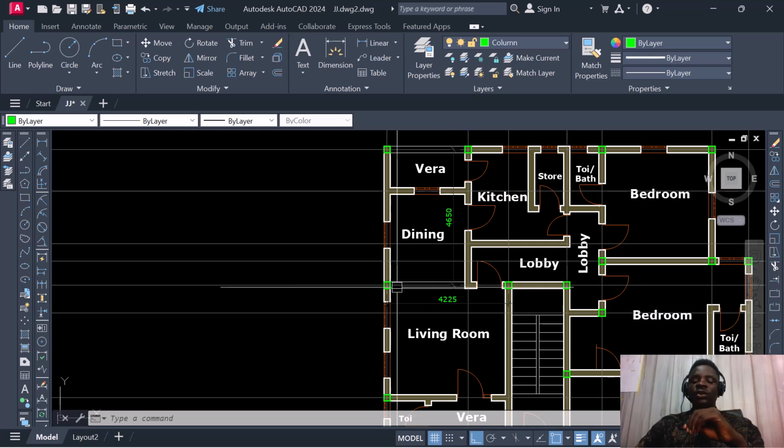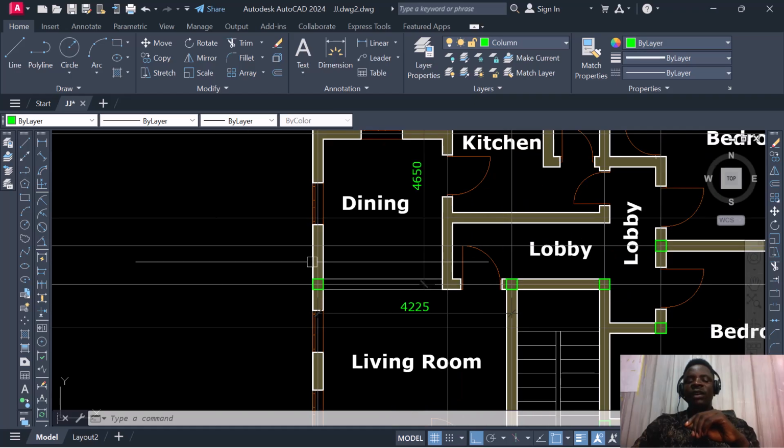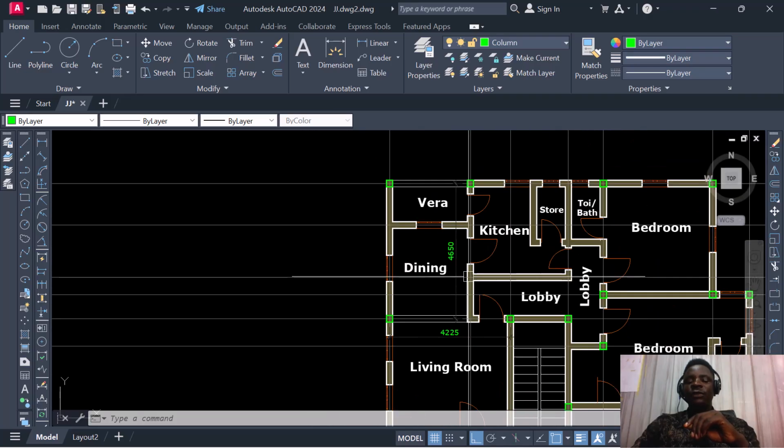So if you look at this situation, you can see we have 4 meter here, and we're going to have this secondary beam. So this is going to be beam to column, because the beam is moving from this column down to this column. From this column, we're going to create a beam over this region. And if you look at this situation here now, almost the same thing. So this area, we have a column at this end, and we'll have a beam supporting. So this beam is going to be a secondary beam because it's going to rest on this primary beam.